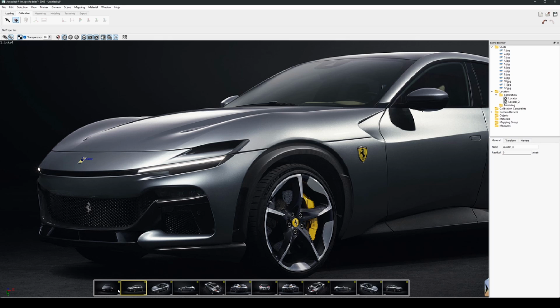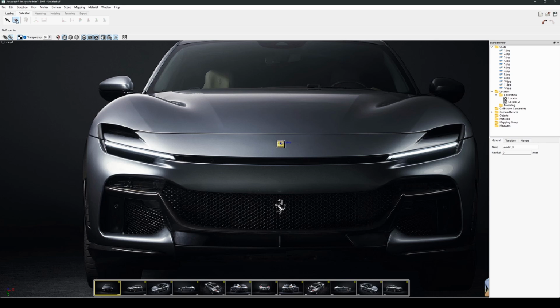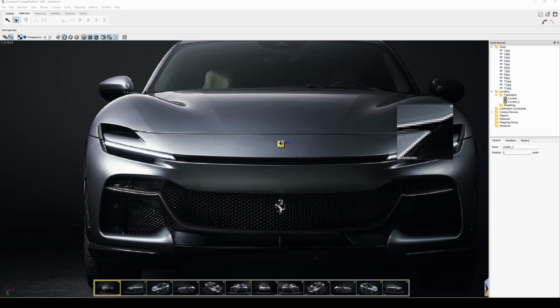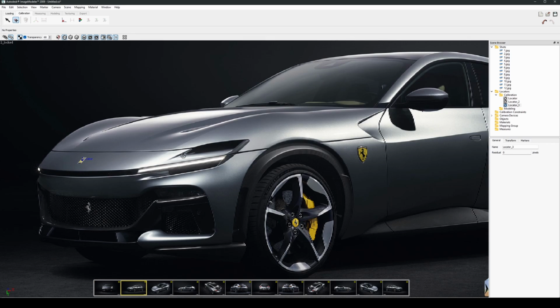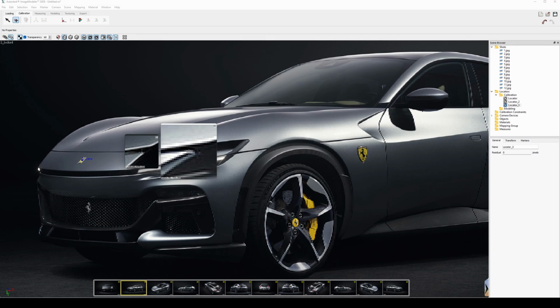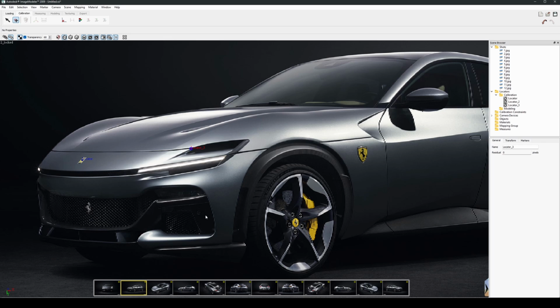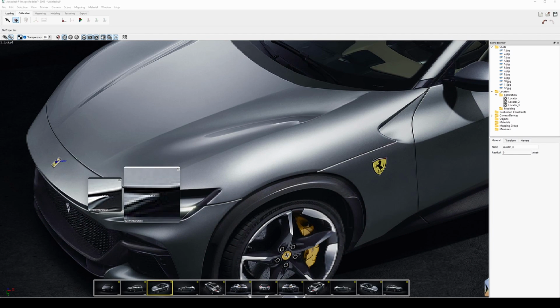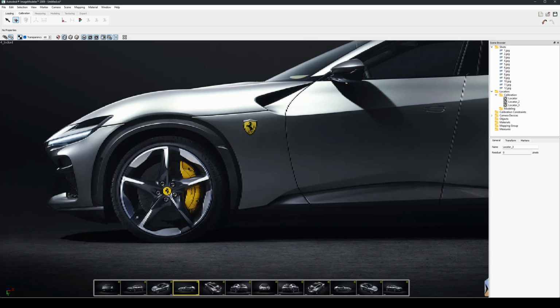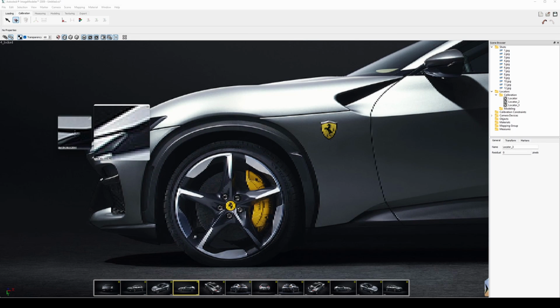The best thing you can do instead is to add in that locator to about somewhere here. Now this should be an easy to spot area in most of the images. So I'm just going to left click and then release to add in that locator there. And I'm going to move to the second image, and you can see it's easy to find. So I'm just going to add it in again to about there. And I'm going to move on to the next image. Easy to find. I'm going to add it in about there. And that's basically the idea.